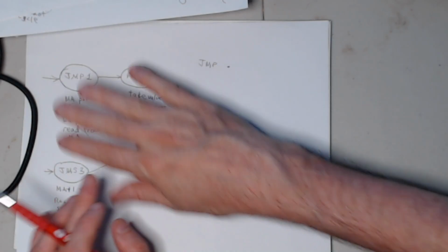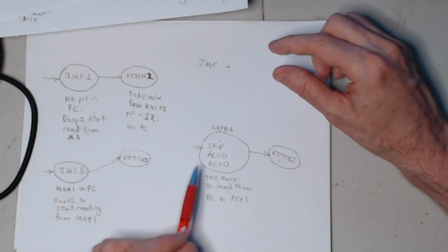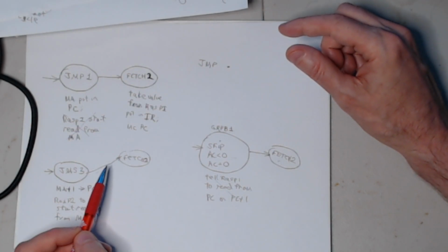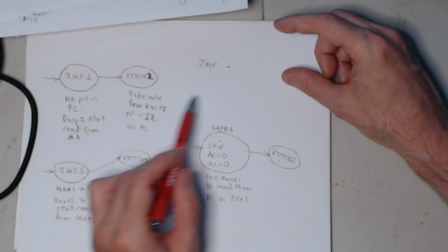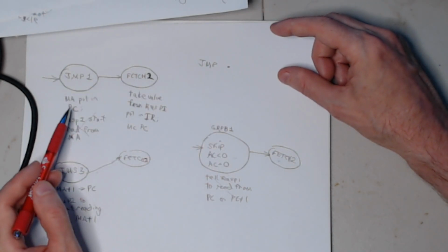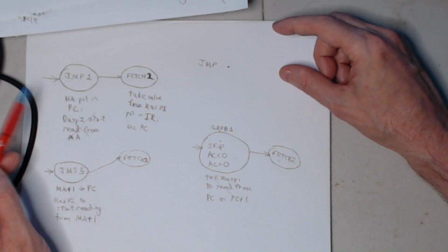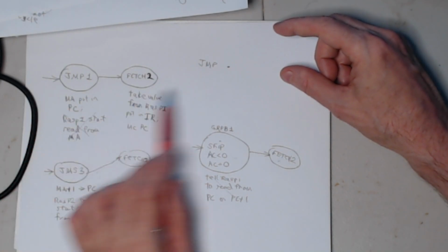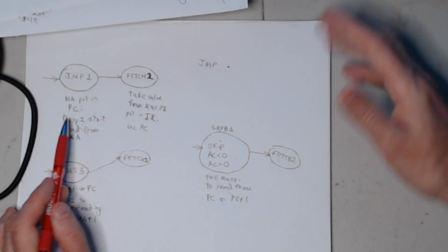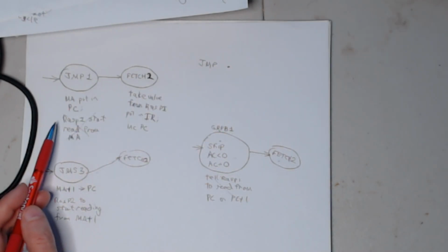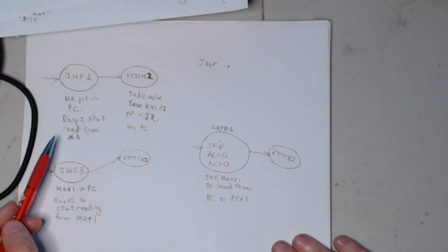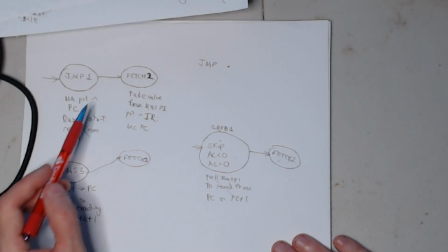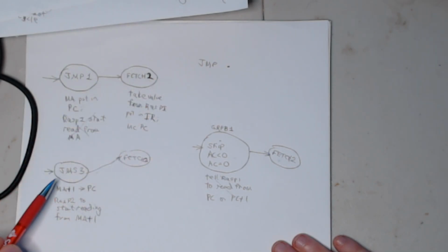So if there's an interrupt request, it doesn't do this optimization. Otherwise, you could end up, like I said, with jump to self getting stuck, and the processor would basically be hung at that point. It would never recognize an interrupt request or anything like that. So you have to not do this optimization if an interrupt request is pending.